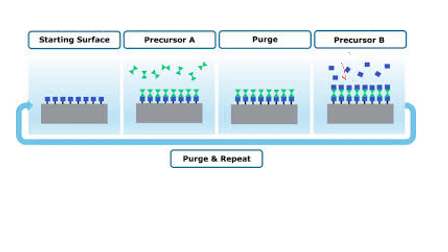So one great advantage of this process is that we can control the growth of the film very finely. Since it is in the word itself, atomic layer deposition, we are depositing it layer by layer. So it actually gives a film with minimum thickness, and we can also control the quality of the film very well in this case. There are several materials which can be deposited using the atomic layer deposition process. Some of them are aluminum oxide, titanium oxide, and so on.